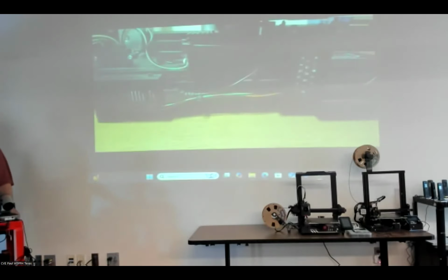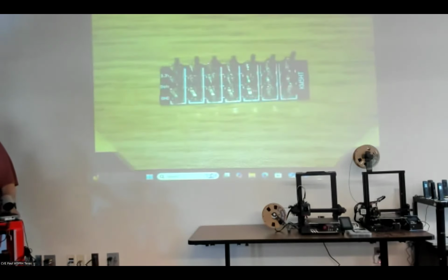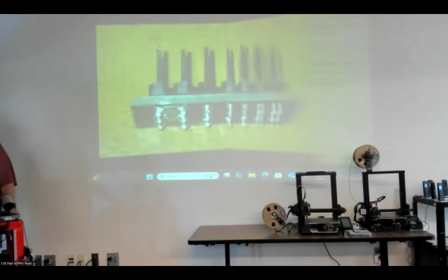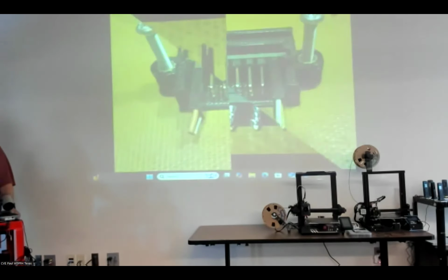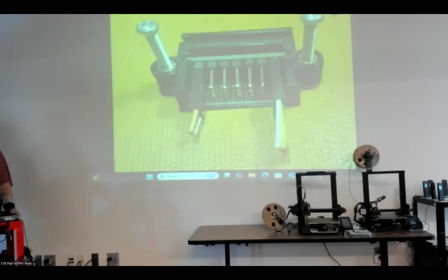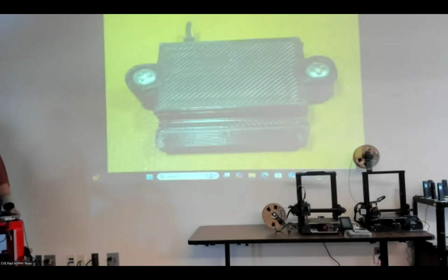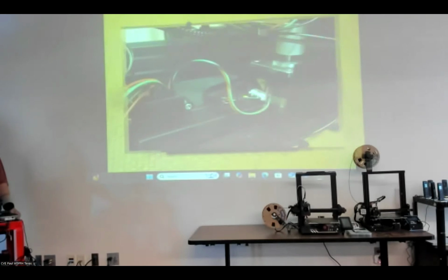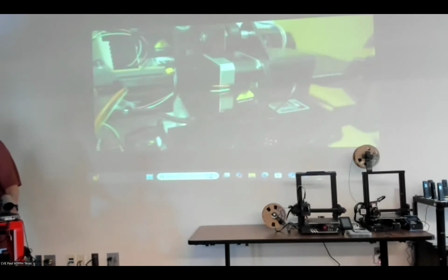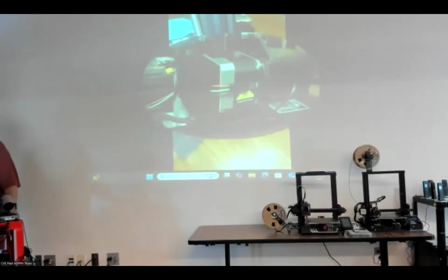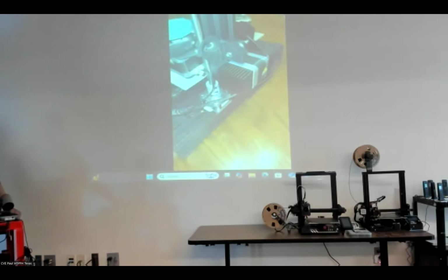When I picked up my printer, I got a spool of black PLA from Micro Center. It worked fine, the whole spool, not a problem. Then I ordered another spool from them, and about every print I started, the first thing the filament would do is break. I got a hold of a bad spool from them. One that potentially sat out too long, so it absorbed moisture. It was sealed when I got it, and it went into a dry box.